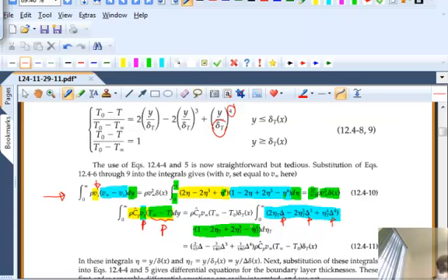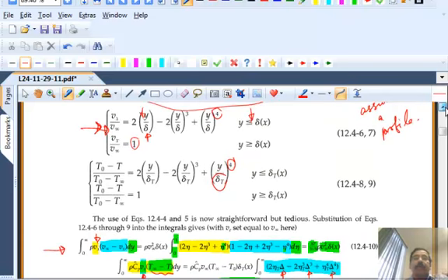In the second equation, the integration is with respect to dy, that is d eta t. Okay, across the thermal boundary layer, because this is the energy equation, the integral is across the thermal boundary layer. But the expression for the temperature profile is already given in terms of thermal boundary layer. But the expression for the velocity, which is the first term appearing here, is given in terms of delta. Okay. Is it the difference between the thermal boundary layer and the momentum boundary layer? The difference or the ratio. It captures the difference between that, but it is basically the ratio.